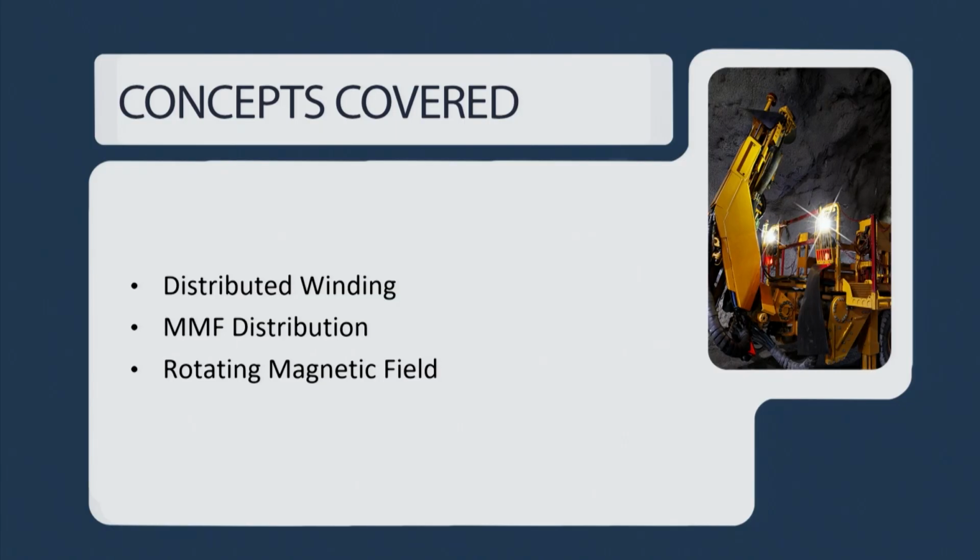So, this creates a rotating magnetic field, as if the magnets are rotated at a fixed speed, even though the actual thing happening is that the current is distributed in the winding, a 3-phase current, and so it is distributed. It happens that it creates a magnetic field which travels around, and it is a rotating magnetic field. We will see how it happens.